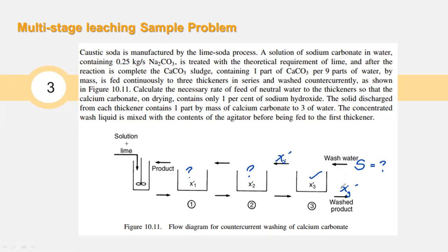These two are to be equal based on the concept of leaching, that the solution that adheres to your insoluble solid in the slurry will have the same concentration as the solution that is present in the overflow. That's the primary principle of leaching.